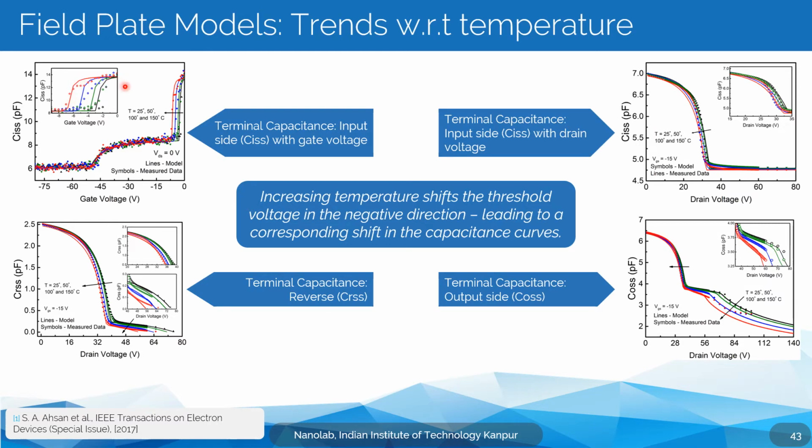As we remembered in the previous slide, these plateaus or humps appear at voltages where the devices turn off. If the voltages at which the devices turn off are governed by the threshold voltage, which they are, and the threshold voltage is a function of temperature, then these humps become a function of temperature.